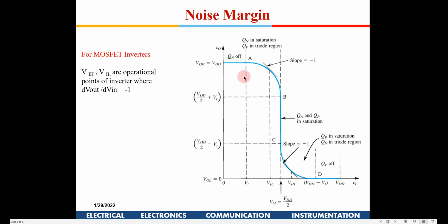That is also possible, certain configurations. Okay, so here this was the kind of VTC curve which we got. So we had to define noise margins to understand how to define a figure of merit which represents the immunity to noise. So here what we did was we defined a point VIL, when this curve starts falling down with increase in input, the output being on the y axis and input on the x axis. When the output starts falling down, we take a point where the slope is -1. So you drop a vertical line and we defined it as VIL.